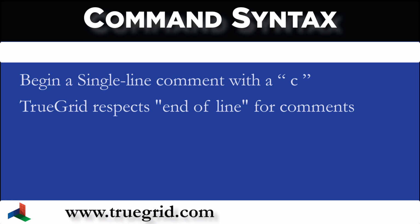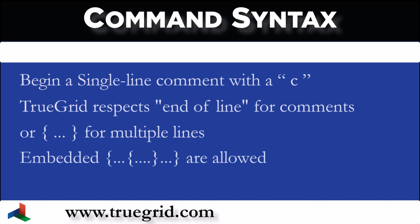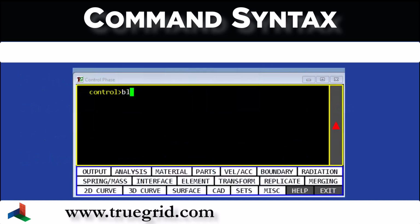Now, an alternative is when you have a group of lines. Could be any number of lines, and you can use the curly brackets here, and anything in between will be ignored. So if I were building a complicated model, let's say with 50 or 100 parts, and I decided that part number 27 should be removed, I would put this curly bracket at the beginning of the part and this closing curly bracket at the end of the part. And then TrueGrid would treat it as nothing more than text to be ignored.